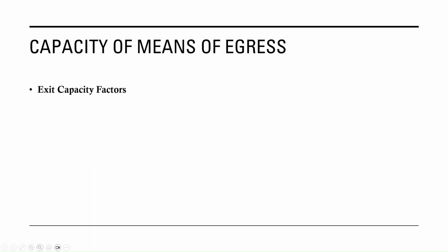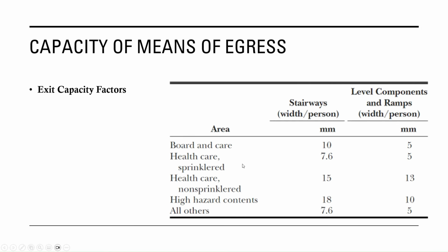Now, let's talk about the unit width factors. In NFPA 101, the required egress width is calculated using specific widths per occupant as shown in this table. For stairs, the factor is higher. For doors and corridors, the factor is lower. This means that a stair serving 200 people will need more width than a corridor serving the same number of people. This is intentional. Stairs are bottlenecks during evacuation, and congestion on stairs is one of the biggest risks in fire scenarios.